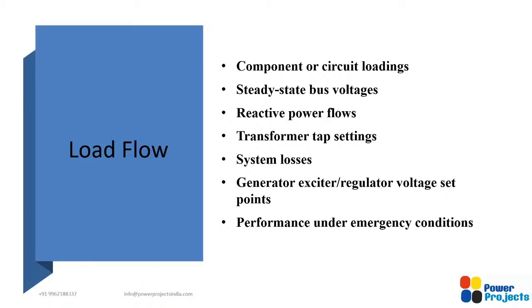This also gives additional information with respect to the transmission lines: what's the available transfer capability or available transfer capacity, that is ATC. So if the transmission line is able to carry 100 MVA, and it is loaded with 30 MVA, how much capacity is still available which I can use for the future? That's the first point: performing the load flow analysis to identify the equipment loading.